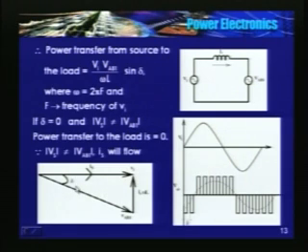Now if I make delta equal to 0, and the magnitude of Vi is not the same as VAB, they are in phase: the zero crossing of Vi matches the zero crossing of VAB, but the magnitudes are not the same. Some current has to flow. What sort of a current now?